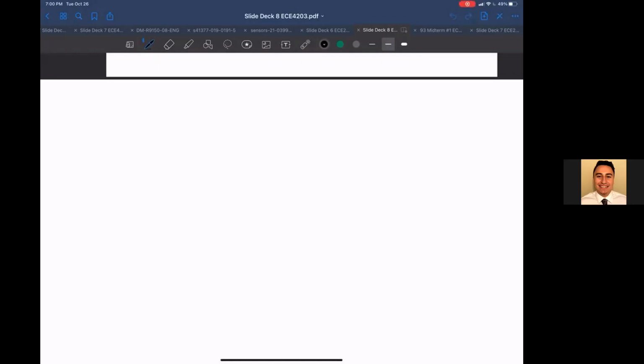I didn't think it was that bad, but the noise margin thing was a bit tricky until you sent out the email. I get confused about the noise margin too myself. I had to get kind of creative. To obtain it, I had to create a line and move the line to the transient points of the graph, and then use the cursors. When the cursors reflected a -1 slope, I took the values and did some quick calculations to determine what the noise margin was. Okay, cool.